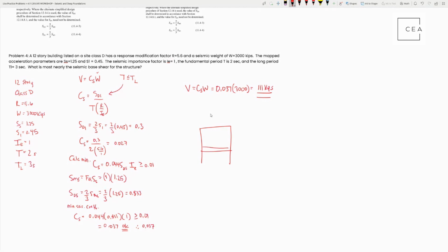So we can say, Isaac, that base shear is kind of a reaction to all the shears that are being imposed on every story going up through that building, right? So you could divide that base shear up just using statics.